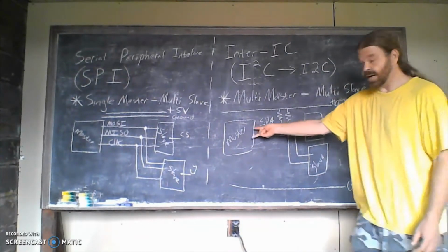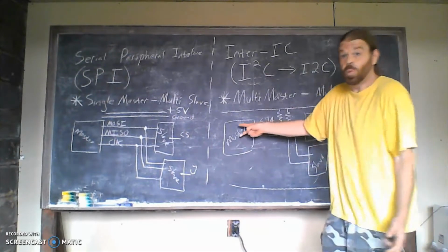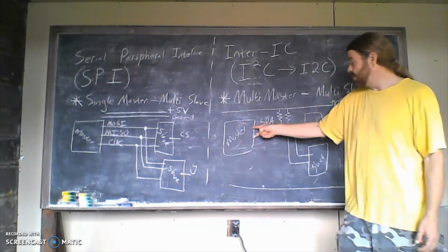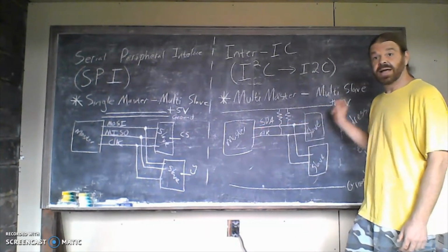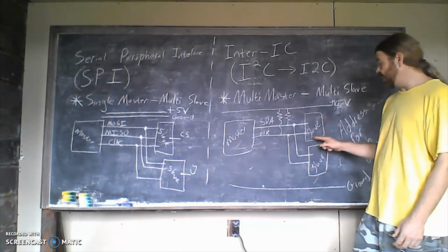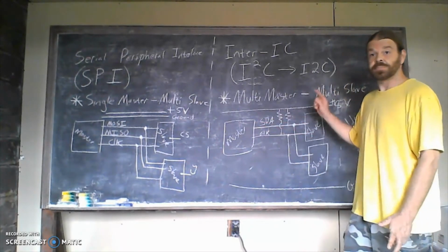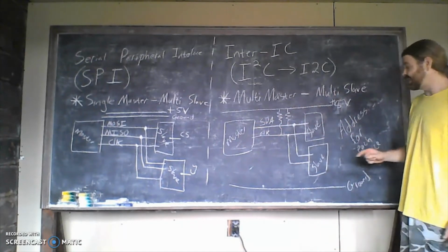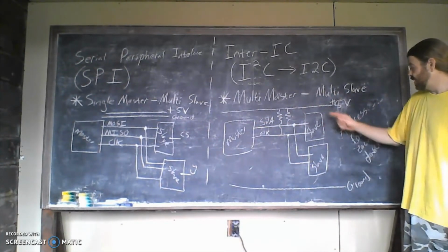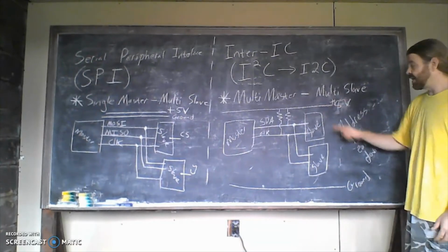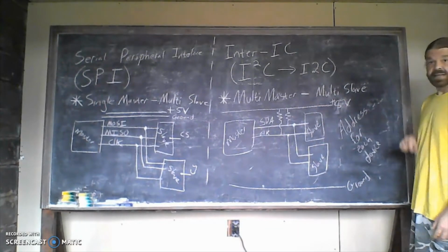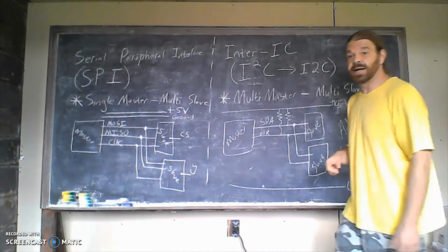So we keep a high voltage, we keep a 1 on both our lines, and as soon as something needs to communicate, it sends a 0 down both lines. Then everything knows to listen as soon as it finds a 0. And as soon as the 0 comes down the line, everything listens, and the next thing coming through will be an address.